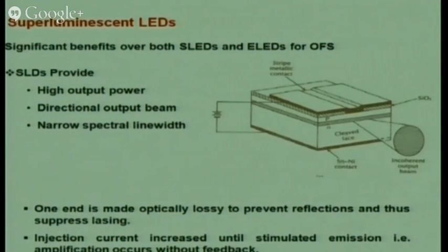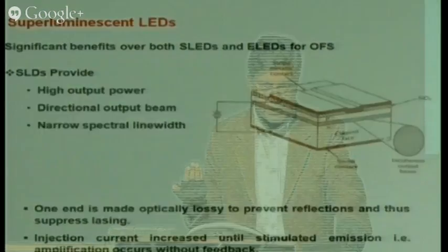So we have the stimulated emission within the active region, and then it produces a high output. Rather than spontaneous emission, stimulated emission gives me larger output plus coherency. Right? It has slightly better coherency as compared to LEDs, but lesser as compared to laser diodes, where the mirrors are parallel. So this is another area we have seen during Deepavali time.